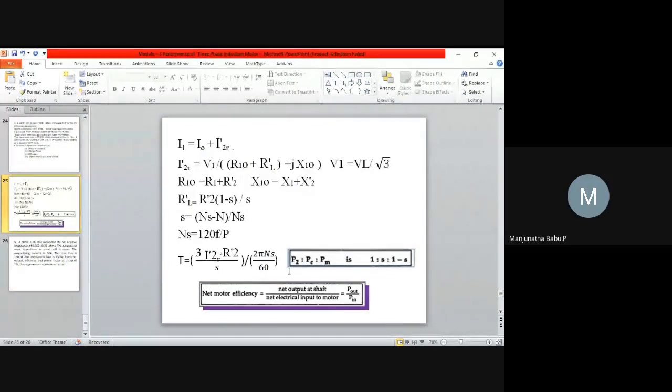We're getting 0.46. 36.23 is in kilowatts, so it will be 0.46 kilonewton meter, or 461.53 newton meter. That is the torque.